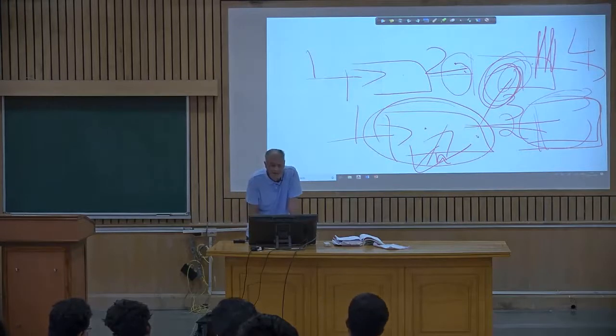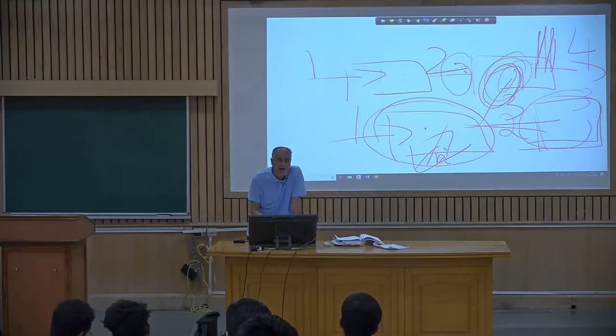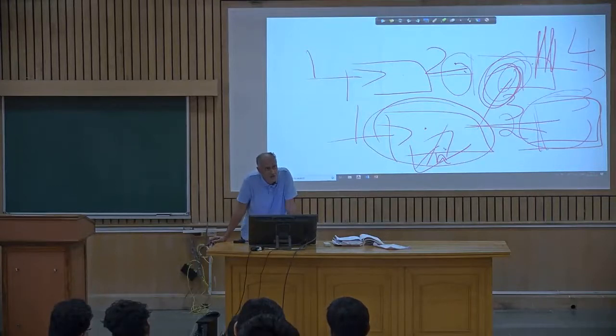So I'm just saying this arrow is for a material coming in. I can have heat come in, correct? Or heat go out. I can have work come in or work go out. So write the arrows correctly. If you write the arrows correctly and number it correctly, I think it's a piece of cake. This is very, very easy. Maybe the easiest. It's fun also. It's fun for you to write the streams.